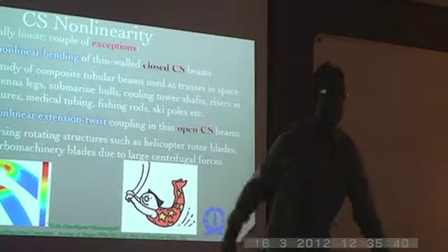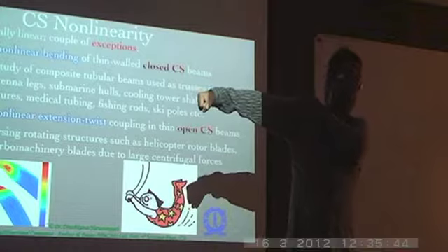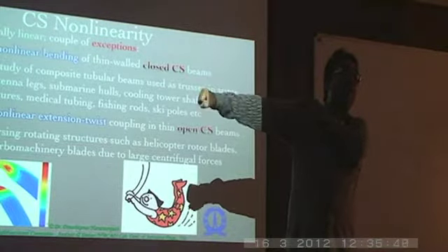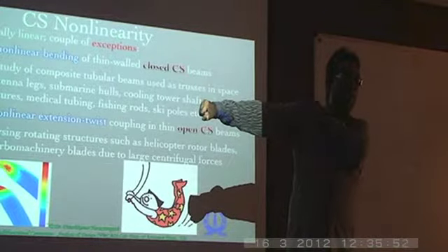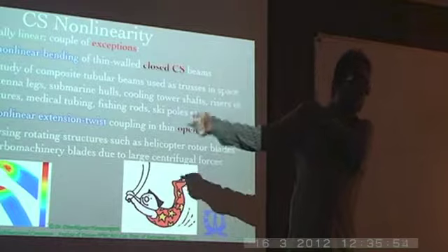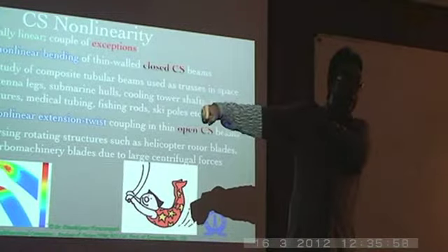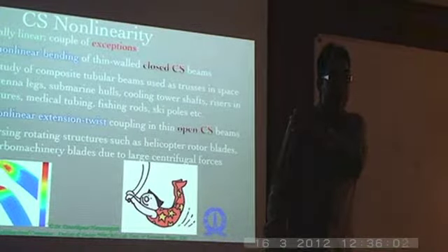Yeah. See, basically in an aircraft wing, they say the tensile loads are not much. Okay, so you would not have this extension-twist coupling being a phenomenon of interest. It's more in rotating structures. That's why we gave the example of the helicopter rotor blade. Okay, so there the Brazier effect would be more important.